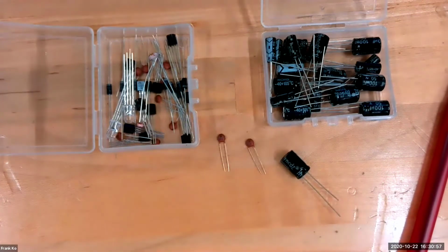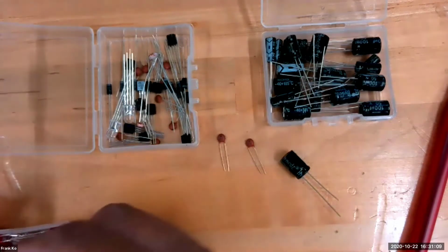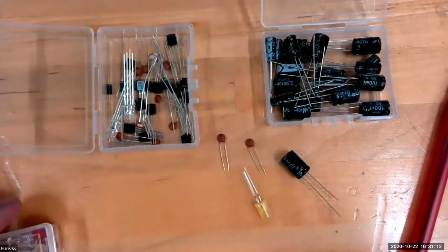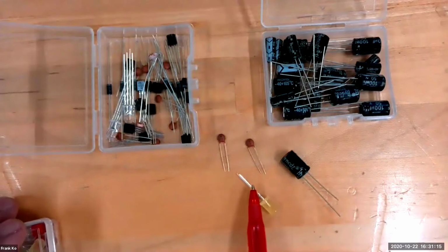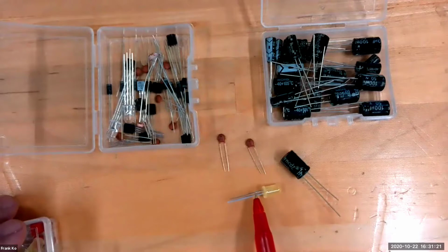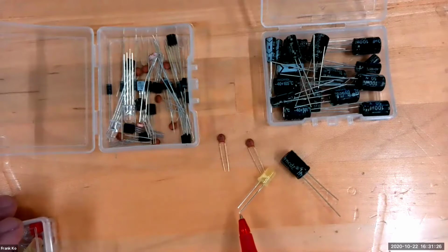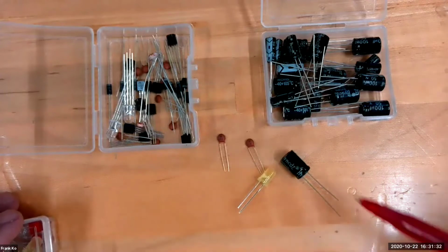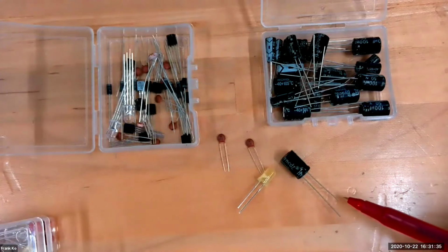It follows the same rationale as your LEDs. When you had LEDs hooked up to your circuit board before, what was the identifying factor that told you which lead of the LED was positive, which lead of the LED was hooked up to negative? Was the length of their leads, right? Remember that, this thing will not stop rolling around. Okay. Remember when we said that for LEDs, the lead that is longer is positive, and the lead that is shorter is negative. So it's positive to be long, negative to be short. And the same thing here, positive to be long, negative to be short. So the capacitor follows the same rationale.